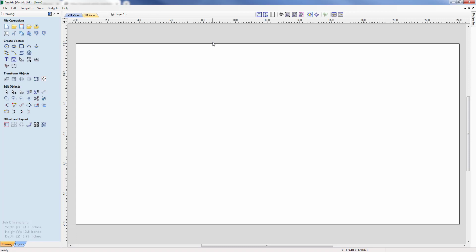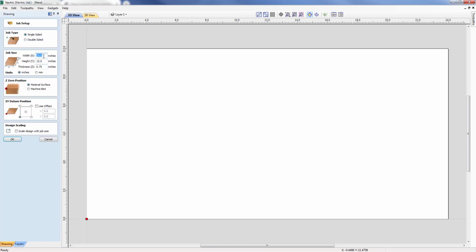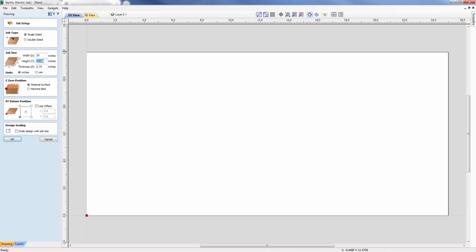So essentially I want my texture to be bigger in X and Y, and then to profile around the edge of a vector in order to trim that up to the 24 by 12. Okay, so with that I'm going to come back up to the form now for the set job dimensions and origin, and increase this to 25 in X and 13 in Y.